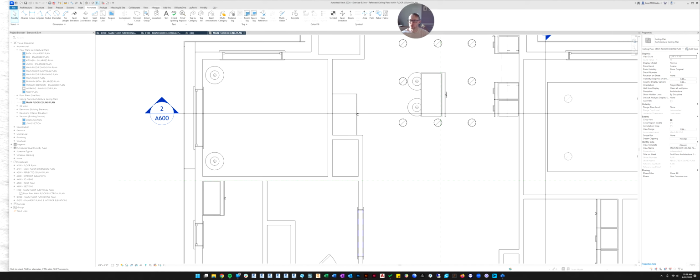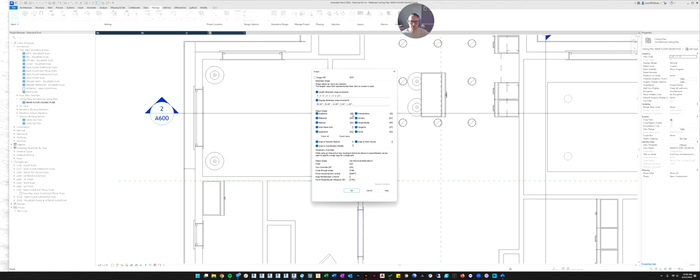If you go up here to the ribbon and click the Manage tab, there's a little magnet that says Snaps. If you click that, there's a drop down. There's like this dialog that shows you all the snaps you can use. So you can turn snapping off if it's annoying you. There are times where the snapping is frustrating. It wants to snap to something and you don't want to snap to it. And there's no way to get it to go where you want it to go because it keeps snapping. So you can turn the snaps off, and to turn the snaps off, here is the shortcut.